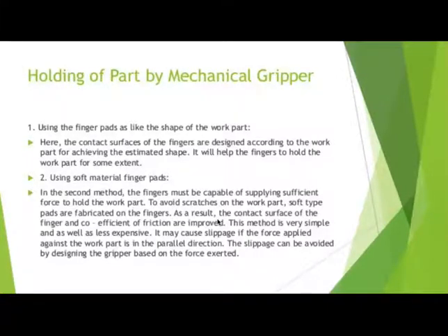As a result, what will happen? The contact surface of the finger and the coefficient of friction are improved. This method is very simple as well as less expensive. It may cause slippage if the force applied against the work part is in the parallel direction. The slippage can be avoided by designing the gripper based on the force exerted, and this is very important.